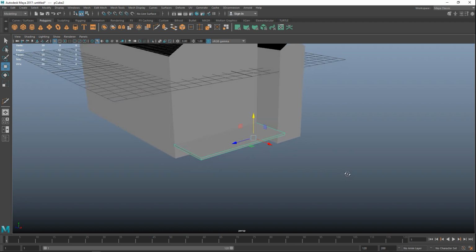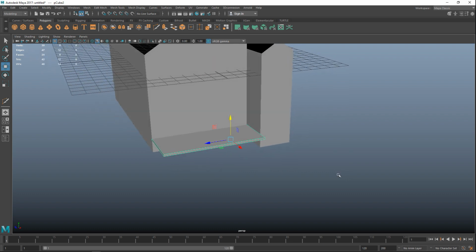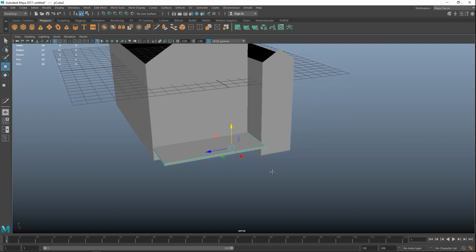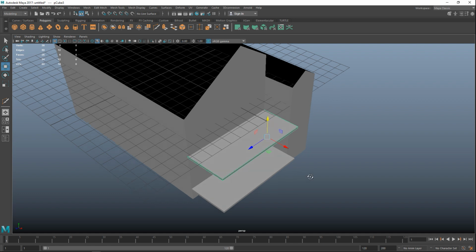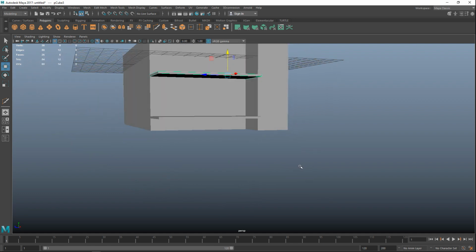And then what we're going to do is we are going to create a number of vertical pillars. Now we don't want too many because at this end the roof of the porch will be connected to the walls and up here as well. But here on the corner and on this corner and right here we want one. Okay. So I need to eyeball the height first. So what I'll do is I'll hit Control D to copy this guy. So I can just bring that up and see how far up I want that to be.